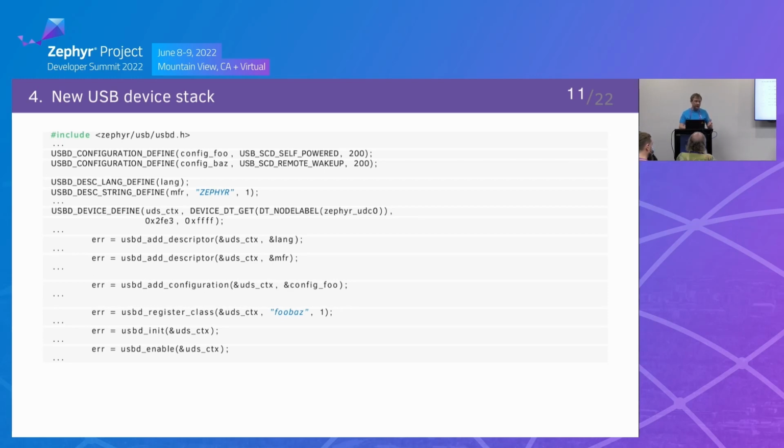We have the same functions in the other direction, to disable the USB device and shut it down, so it will be completely disabled. And in the future, a way to change the role, if the controller is OTG compatible, for example from device mode to host mode.